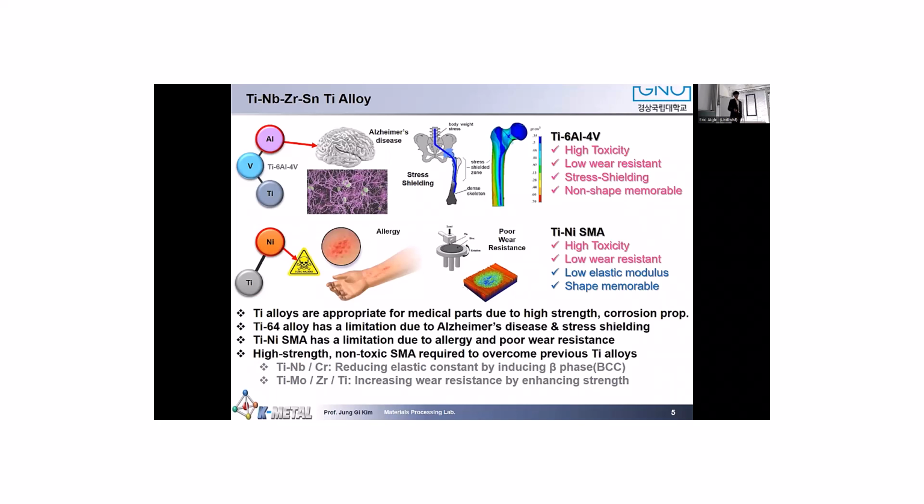started to develop titanium zirconium niobium and tin titanium alloys. Although titanium alloys are quite appropriate for medical devices due to their high strength and corrosion properties, the present alloys have several issues. Ti-6Al-4V has limitations due to toxic species like aluminum, and has a stress shielding effect due to its high elastic modulus compared with our bone.